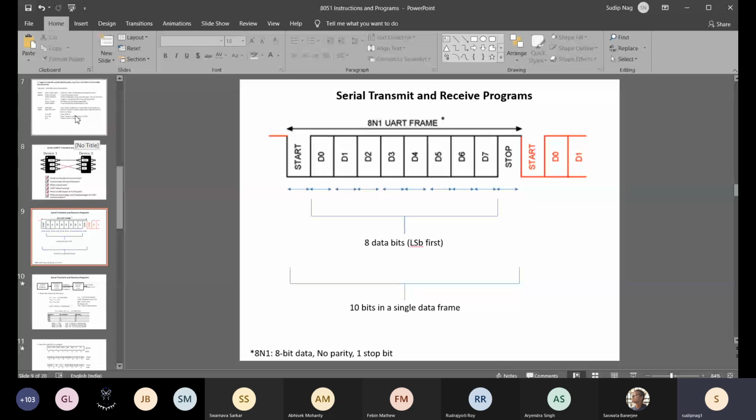For that to happen, we have to further divide it, because the UART standard speed is significantly low as compared to those megahertz values for the crystal. Typically it is up to several lakh bits per second, whereas this is several million bits per second, right? This clock is in megahertz and this is in kilohertz. So the UART typically works in kilohertz, as you can see later on.